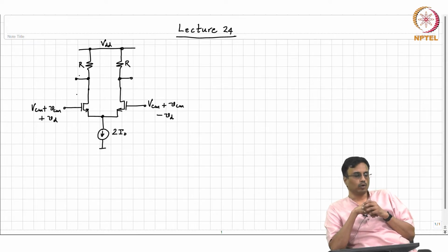So, the first step in the whole process is therefore to design a gain stage that only amplifies the difference. All the gain stages we have seen so far, for example the common source amplifier, amplify only a single voltage, and using the intuition behind the common source amplifier, we eventually came up with the differential amplifier. We have done it with NMOS transistors. There is no reason why the same thing can't be repeated with PMOS transistors.